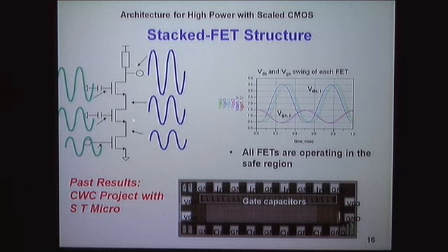So we're going to have to stack it. That was the unfortunate part, realizing that you have to stack it. But fortunately, we've done stacked PAs before. In cooperation with ST Micro's foundry, we built stacked PAs. In this case, this is single-ended. This is not switching. But we found out that, hey, we can stack PAs in order to improve the output impedance and also basically get higher voltage for the same current so we can get more output power, so that you can achieve that 27 dBm, which is really maybe you need 2 watts of peak output power